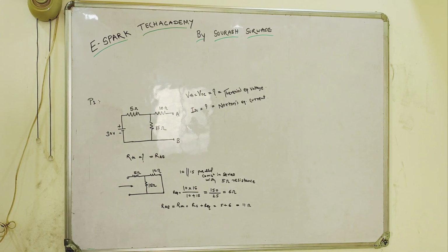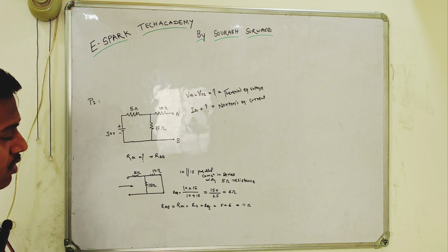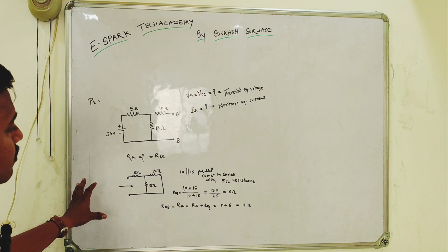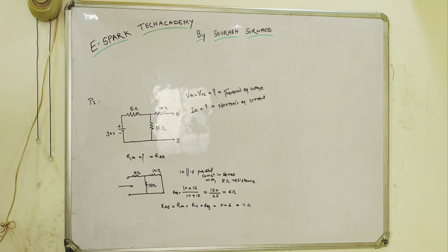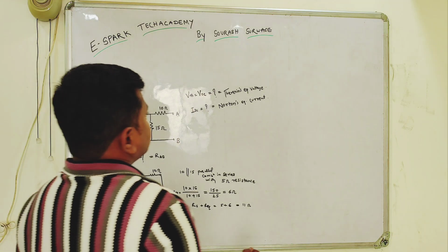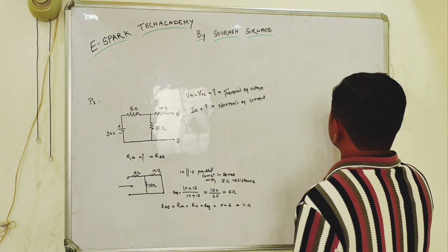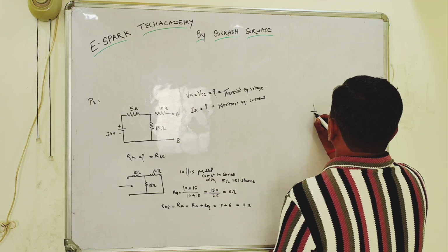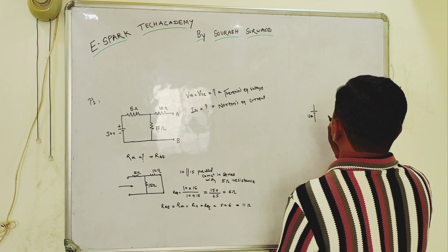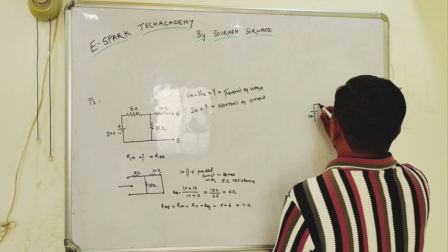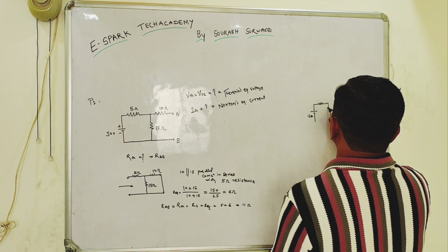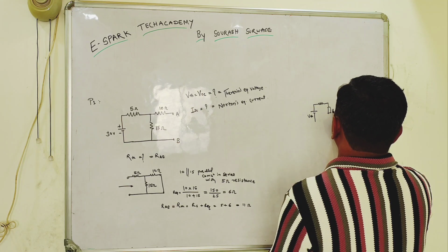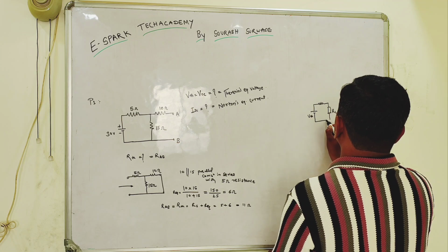The RTH is nothing but RAB, you can say. This is the common resistance value which we will be finding to calculate both the Thevenin's as well as Norton's equivalent. Now in Thevenin's equivalent, what we will do is we will calculate one voltage VTH and it will be connected with a series resistance and RL will be the load.